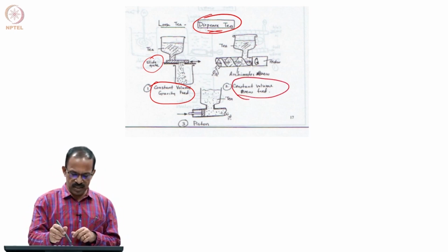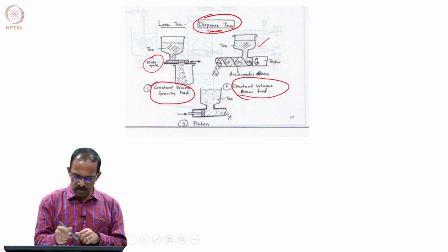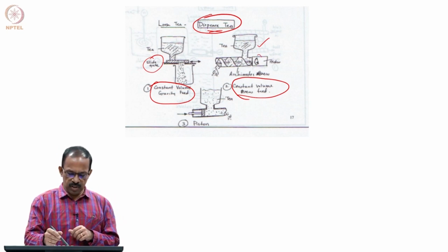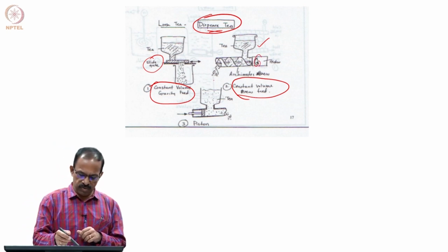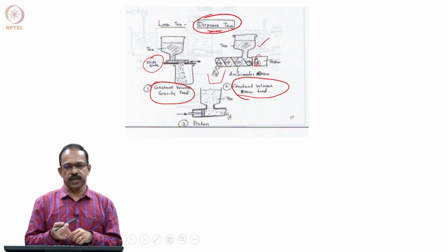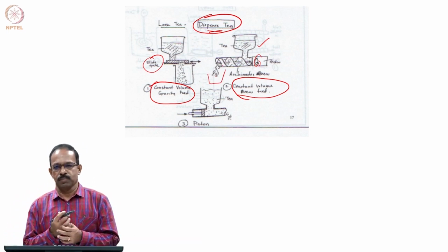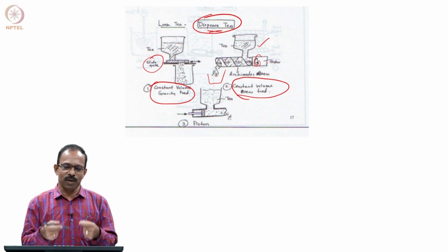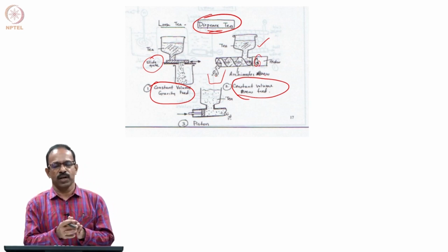Now assume that there is this tea hopper storing the tea leaves, and you have a screw feed, a motor and a screw, and then depending on the number of rotations that you make using the motor, you will get a fixed amount of tea leaves coming out here. That can be another idea to solve this problem. Depending on the number of rotations the motor makes, you will get the amount of tea, so you can actually control it also.